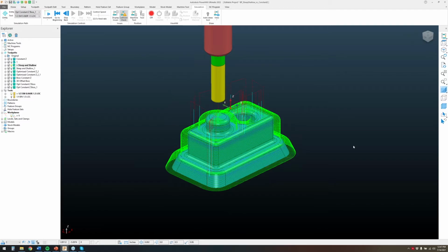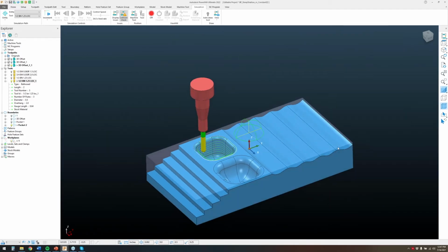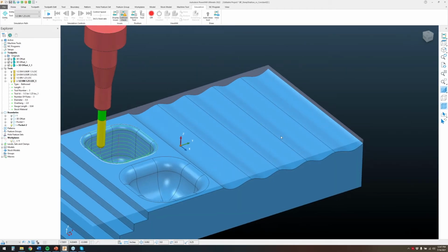So always remember 3D offset finishing, utilize that ball nose. This is not if the surface is flat. Toolpath with not flat surface, just like the wave or the whoops over here. If you did utilize this toolpath with maybe a bull nose end mill, it won't machine the way you want it to.